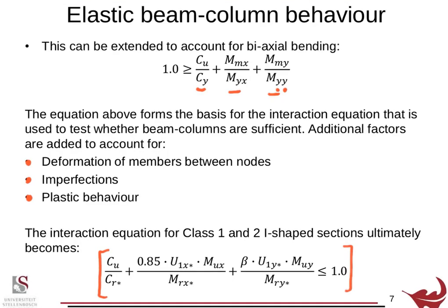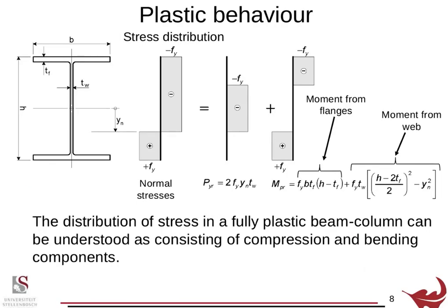And this forms the absolute basis of everything we're going to be doing in terms of the checks. So we're going to be having a look at stresses and forces axially, stresses and forces for moment about strong axis, stresses and moments about weak axis, and checking that all of them together will give us a member that is suitable. But firstly, before we go into that, let's just think about plastic behavior when we try to incorporate it.